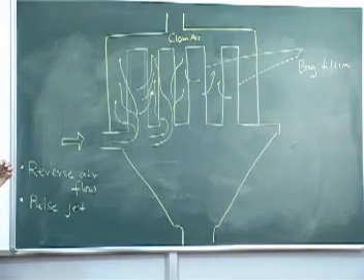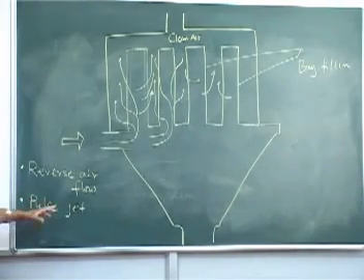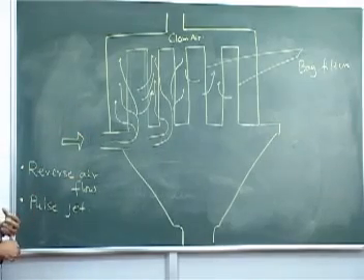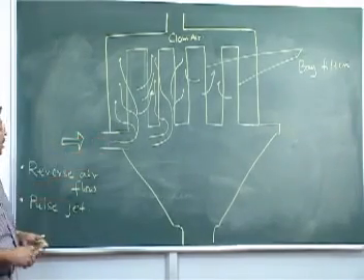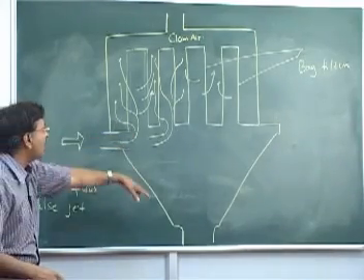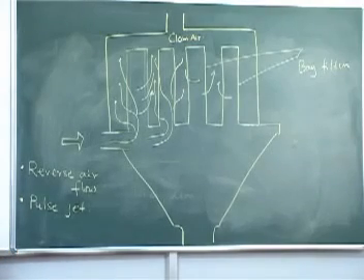Then you pass an electric pulse or some kind of pulse that will shake the things very quickly, and with a lot of energy. In the process of the pulse jet, all the dust will fall, and the bag will again erect. All this happens electronically and computer controlled, and so you can just remove the dust, and the dust will eventually fall onto this one.